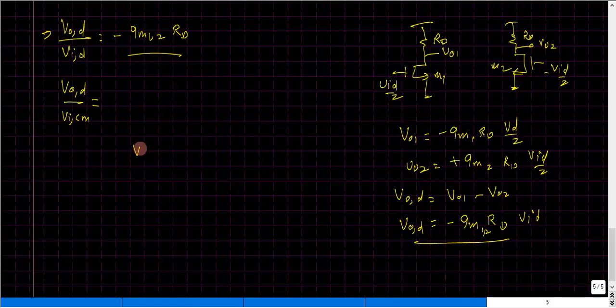So what I'm trying to say is my VO1 would be exactly equal to VO2, and when we take the outputs differentially, that is VOD, which is VO1 minus VO2, then obviously this expression would lead to a value of 0, and because of that I can apply the value as 0 for the second permutation signal.